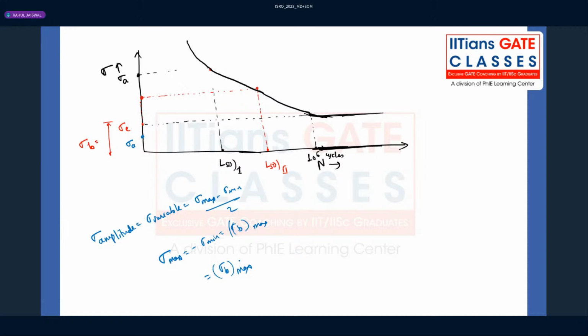Now when you reduce this bending stress further to below the endurance limit, even though you just apply 5 megapascal plus 5, minus 5, plus 5, minus 5, plus 5, minus 5, you will be getting infinite number of cycles. That means you just rotate the shaft and come back after 10 years, and you will see that the shaft is still rotating, it is not failing. Again, the shaft is having infinite life.